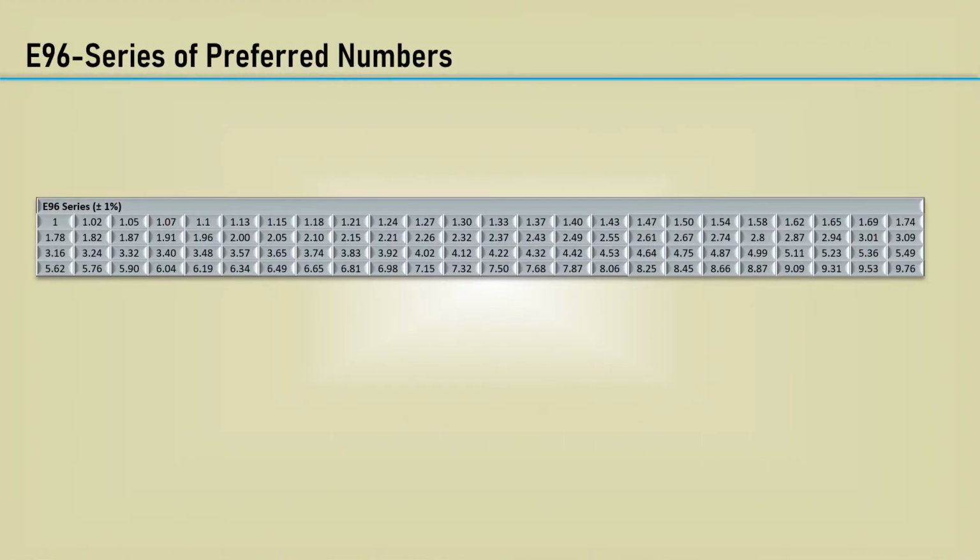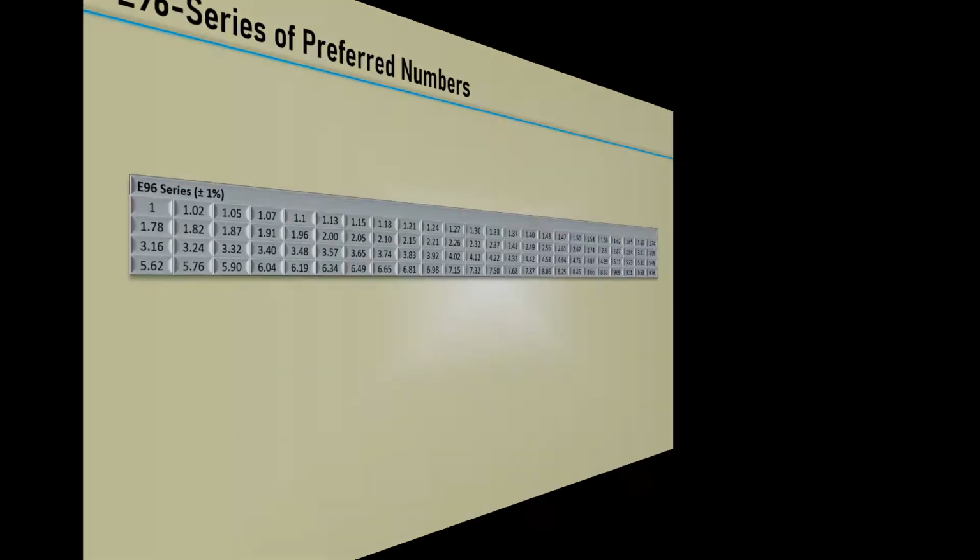We wrote some simple VBA code to return the nearest E96 value of an input. Due to the strict logarithmic spread of the E96 values, that was very straightforward. To do the same with the E24 series and lower, there are values that do not follow the pure logarithmic spacing, and those exceptions will need to be handled in the code.